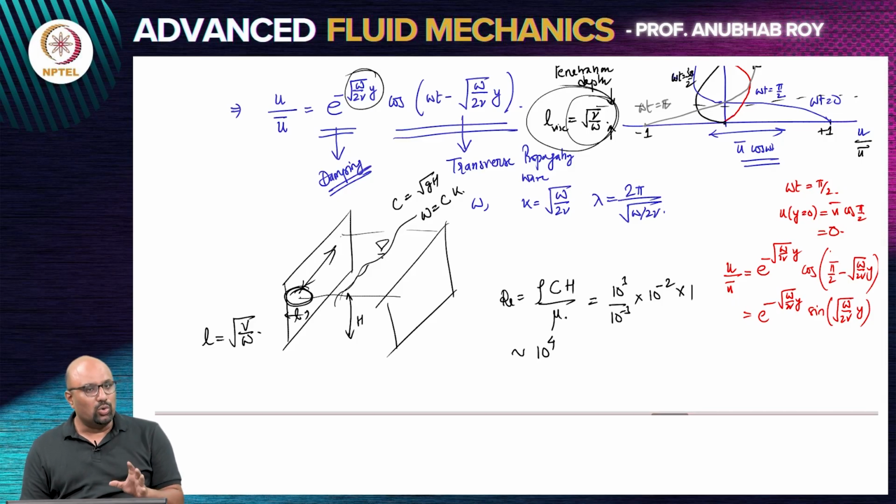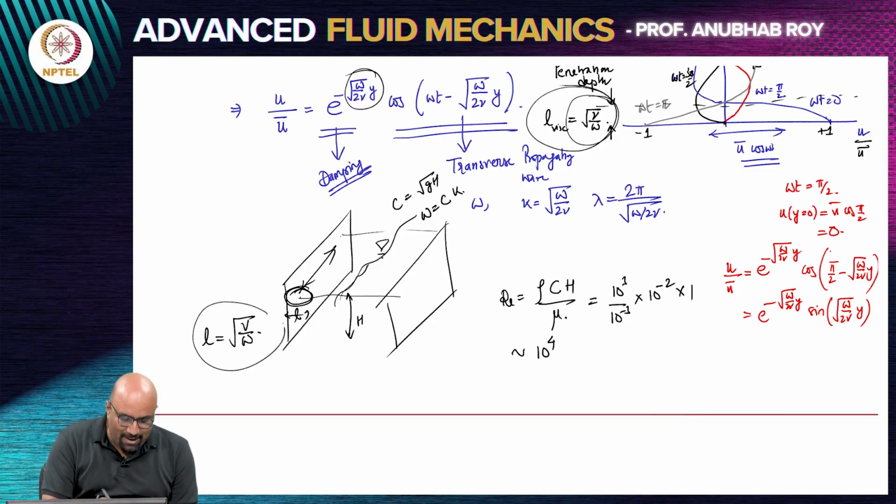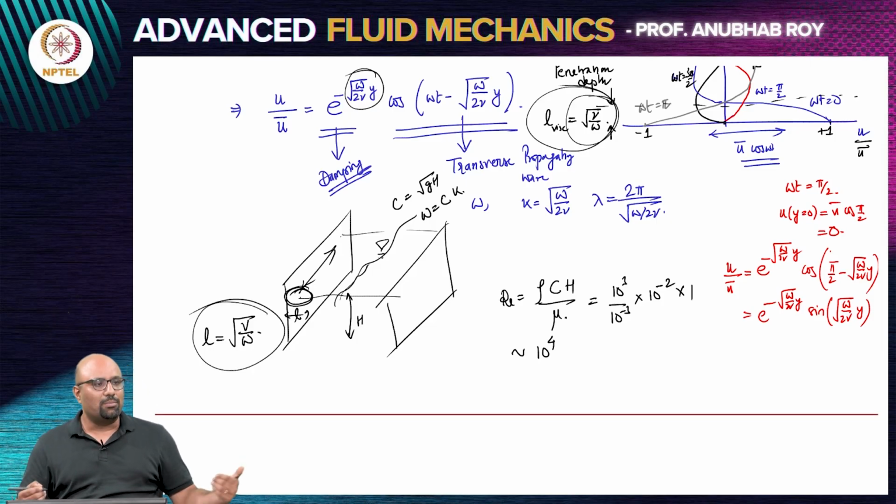So what you can do, obviously if you are able to solve this problem numerically with applying a no slip boundary condition on all sides, that is perfect. That basically takes care of all your problems and you are doing an exact numerical calculation of the problem. But it is also perfectly fine to solve this problem as if there is a flow, the effect of the boundary is replaced by a damping that occurs from the side.